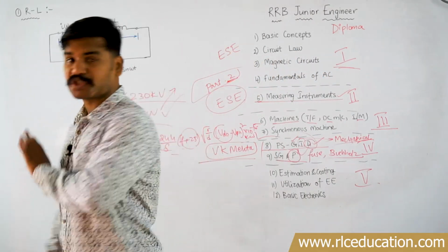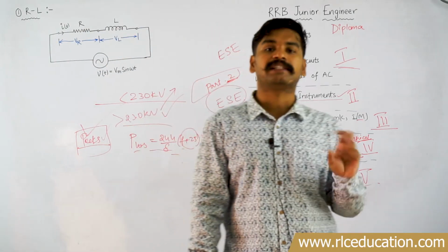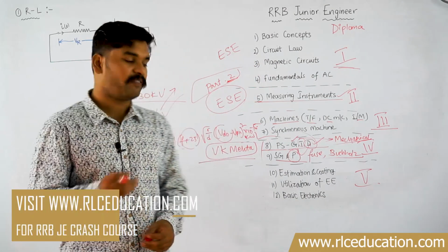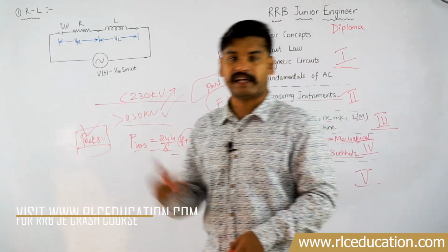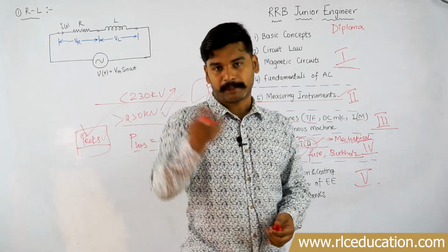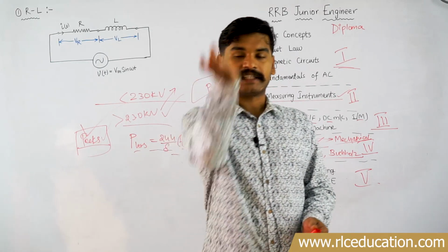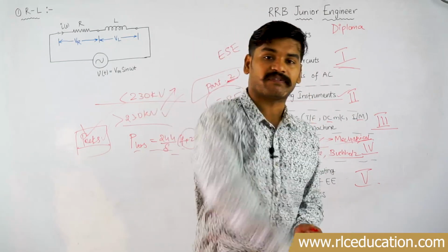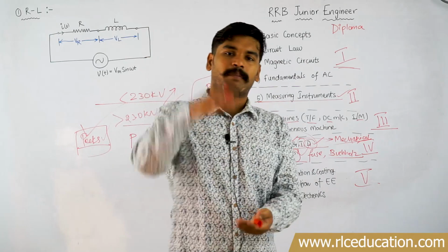Without insulators, there is no electrical system, not just a power system, nothing is there without insulators, because an insulator is a device which avoids the flow of currents in unwanted paths. Current is a very childish thing, it always tries to flow wherever there is the least resistance or wherever there is a conducting medium. But the towers which you use in a transmission line are conductors because they are metals. You are using towers to hold the transmission lines, so there is direct contact from the conductors to the towers. So there may be a chance of an LG fault or current leakage. So you have to isolate the conductor from the tower by using a set of insulators.